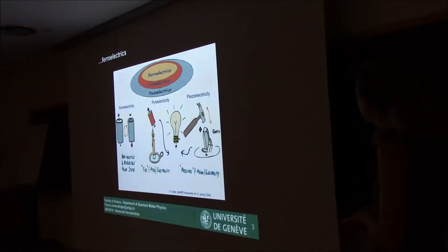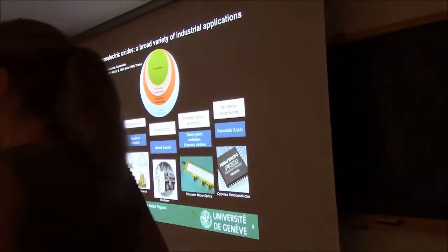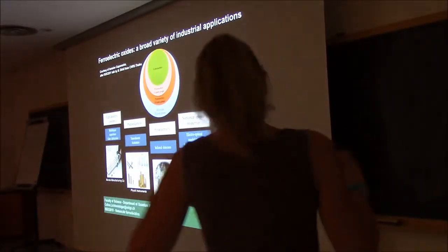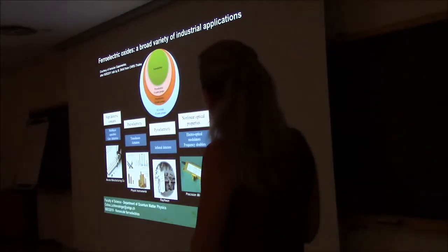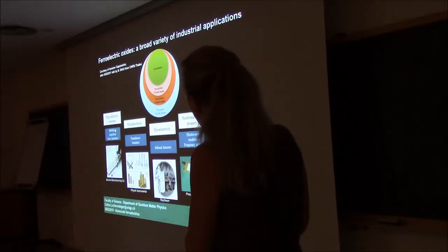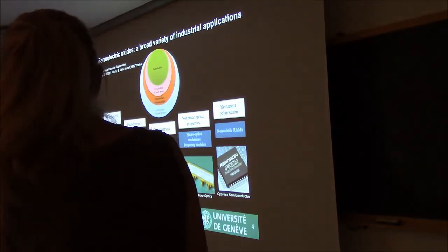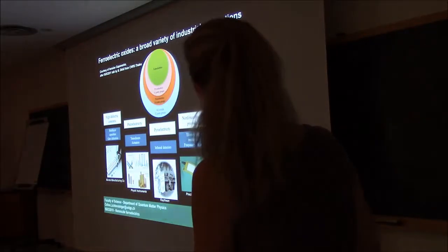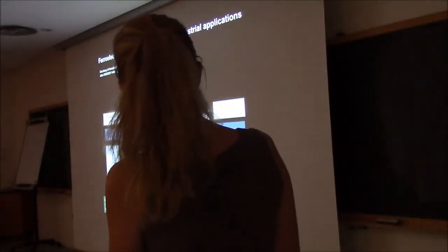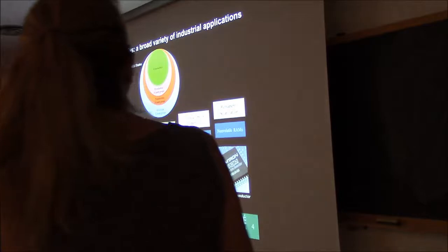Okay, so ferroelectrics are fun at the nanoscale also. And why is it interesting? Because nowadays, there are already many applications that use ferroelectrics, and more specifically ferroelectric oxides at the nanoscale. So here are just a few examples. They are used for the high dielectric constants as multilayer capacitors or gate dielectrics. They are used also for their piezoelectric properties as transducers and actuators, for their pyroelectric properties as infrared detectors, for their nonlinear optical properties as electro-optical modulators or frequency doublers, and for their remnant polarization as non-volatile random access memories.